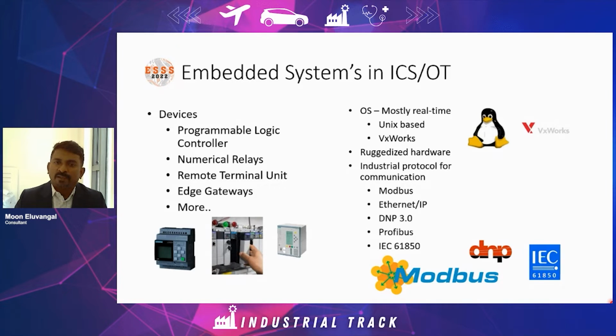It can be an automatic control wired to the breaker. This means when a fault is detected in the system, suppose an earth fault or some other kind of fault, then automatically the breaker is opened. That is done through a program, using either numerical relays or remote terminal units. Sometimes it is done manually from the SCADA software, where somebody clicks a button and the breaker is operated. So these are the different embedded devices used, and I briefly mentioned their purpose.